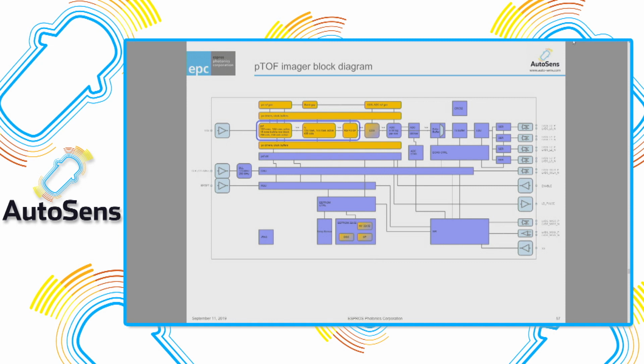And the output data rate, if the data would not be filtered or analyzed on the chip and the data amount reduced to just the useful information, would be more than 30 gigabit, so a lot. The circuitry here does a kind of echo detection and packet generation, and then the imager sends up to 3 echoes per pixel to the host controller.